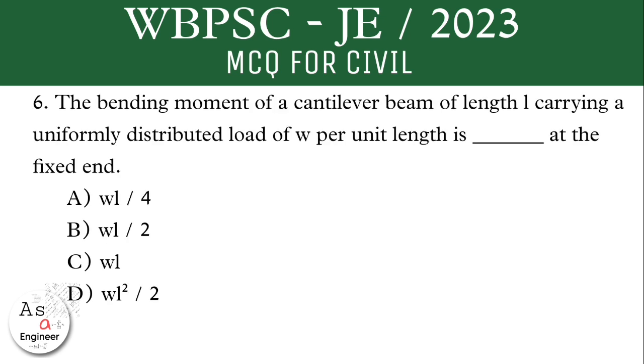Next question. The bending moment of a cantilever beam of length L carrying a uniformly distributed load of W per unit length is what at the fixed end? The correct answer is option D, WL square by 2.